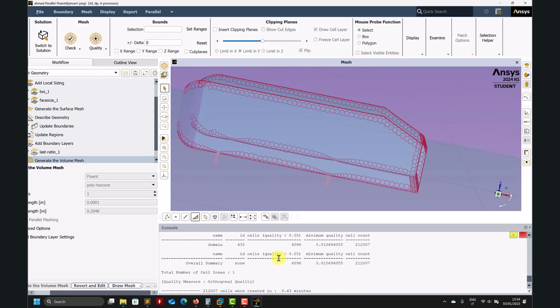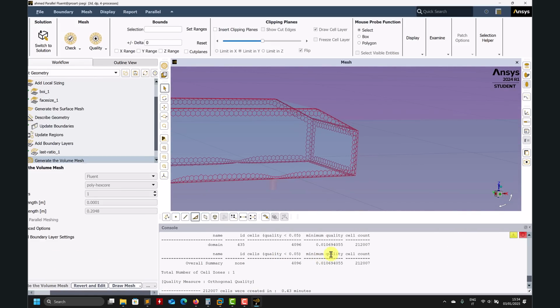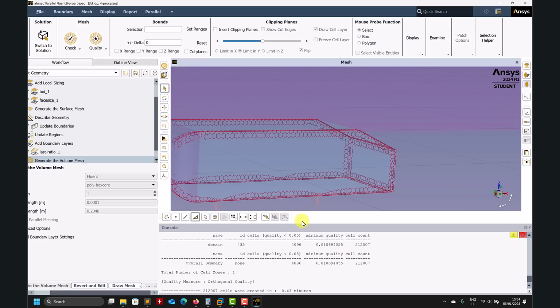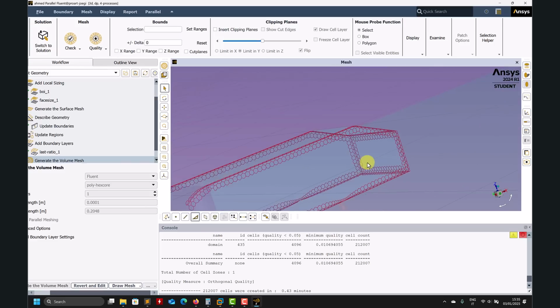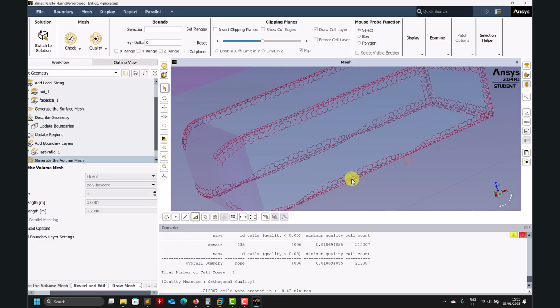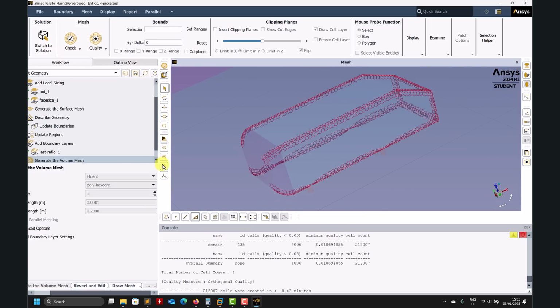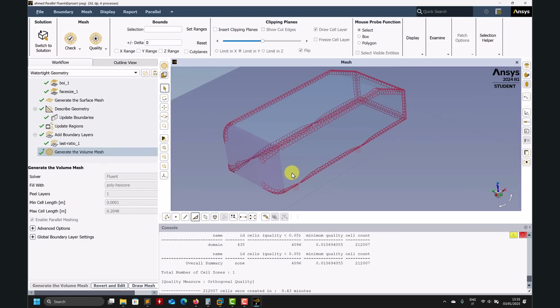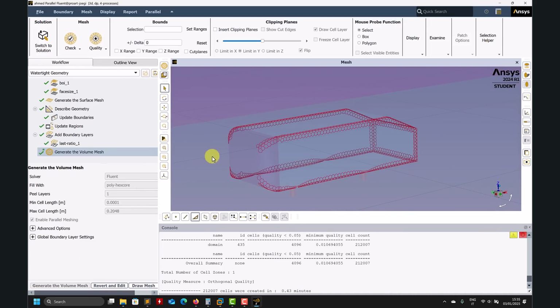This is what I was looking for to get that error. So the mesh is okay. What it's showing you is where you have likely high aspect ratio, high non-orthogonality. See that here it's showing me non-orthogonality, but I also know that the issue is related to the aspect ratio, which might be a little bit high.